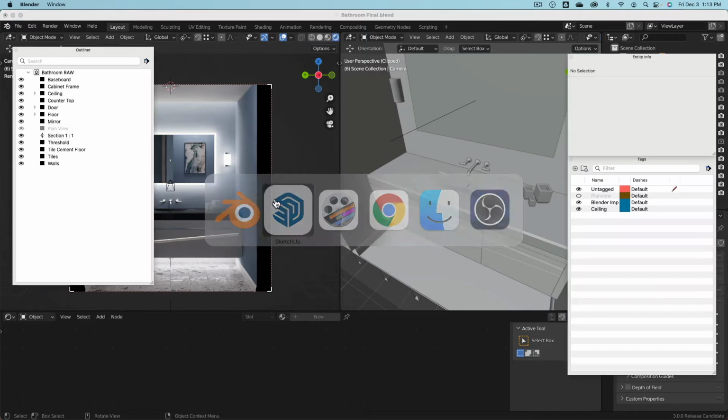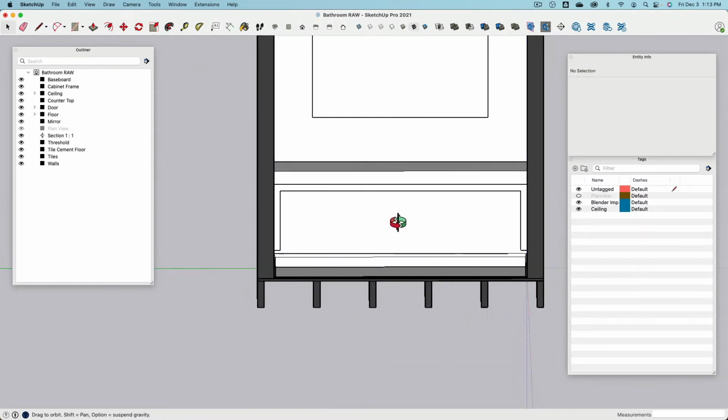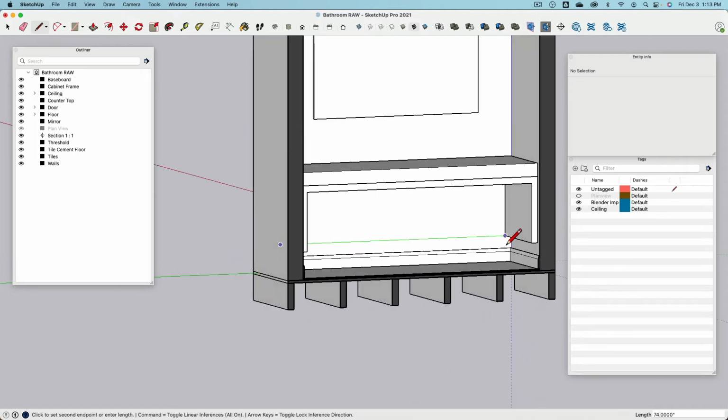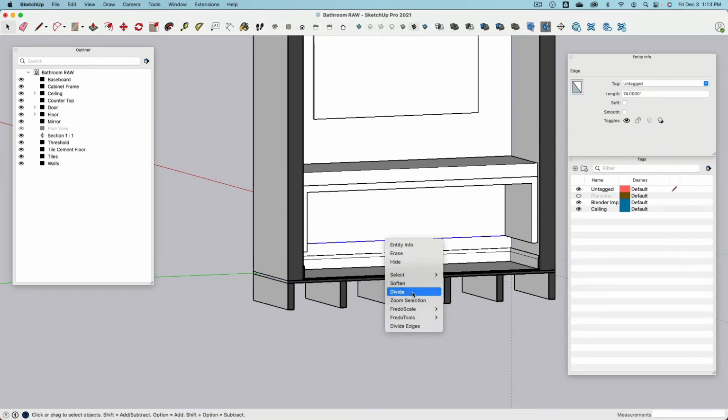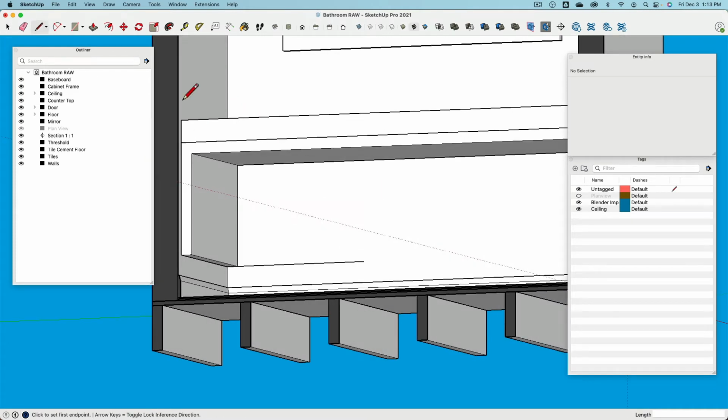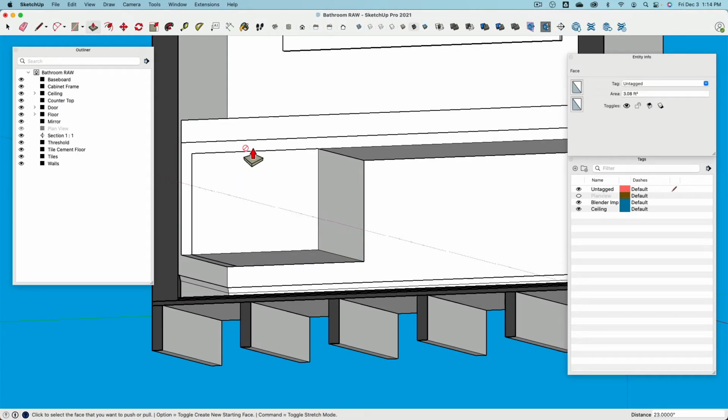And I do 3 here on purpose as an exercise to show you a pretty cool tool we have. So I can draw a line. There we are. Then I will select this line and right click and say, now divide this line, or subdivide, it's actually called in Blender or other programs. Divide, and then type in 3, enter. Then here's segment 1, good night, segment 2, good night, and this segment I will keep. Because now I draw my line up, over, down. There's now my box.